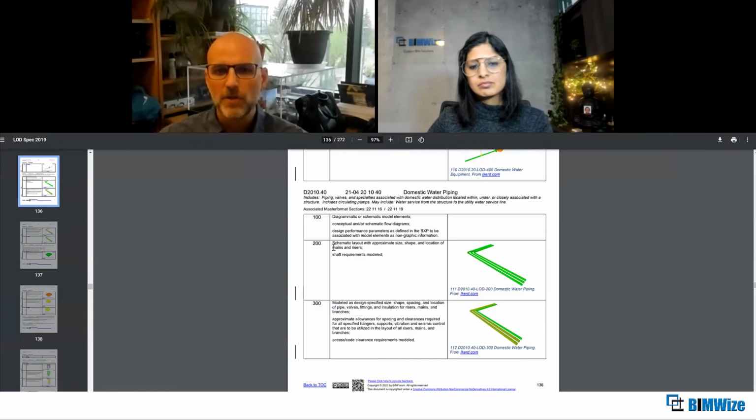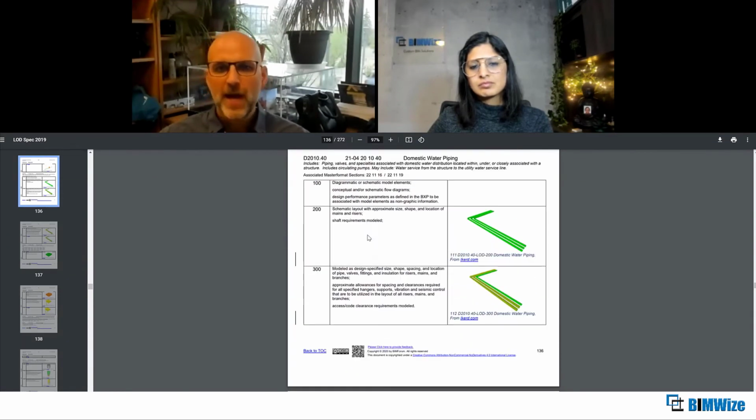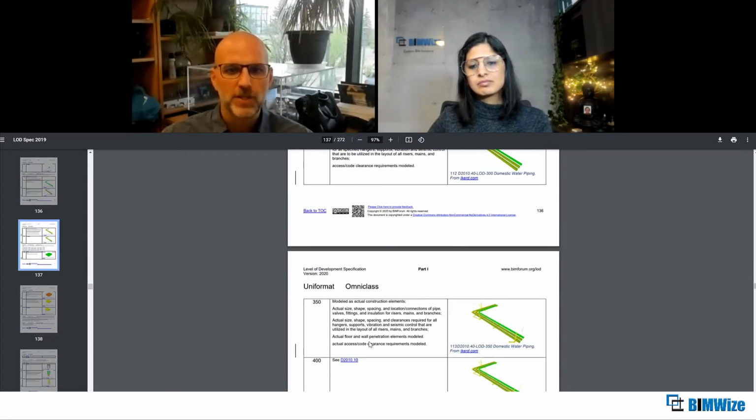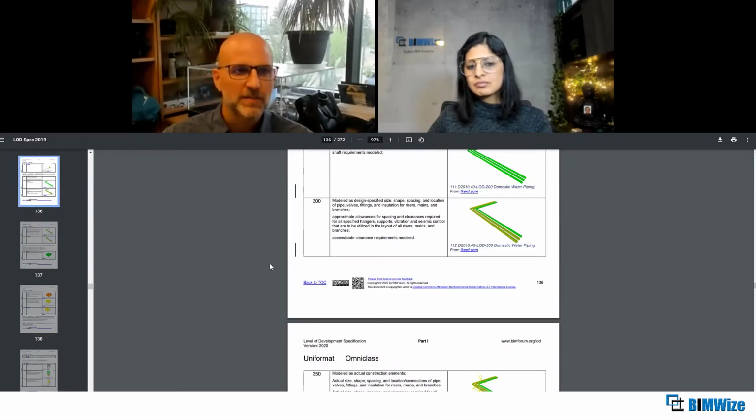When you're talking about LOD 100 to 200, they're sort of assuming that you hand it off, some information gets added to it, it's a little more valuable, then it gets handed off and even more information gets added to it, and it's valuable. So it goes from design to layout to coordination to construction, and that's just a linear process. That's what the whole assumption of LOD is. There's a linear process of where things are defined, and you can just add some detail to add value.